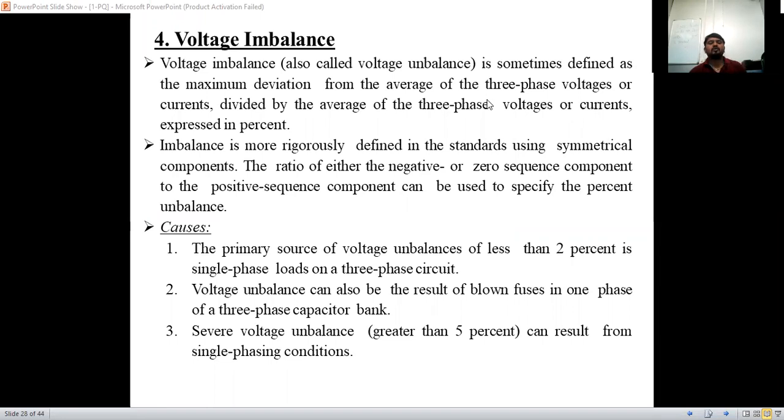Okay, leave that one. These types of voltage imbalances will occur only for single phase loading. Up to your transformer, what will happen? You will get the supply output of the transformer here. The pole mounted transformer is there. You take 3 lines R, Y, B from the substation. You will get a 3-phase 4-line output from the transformer. That is the distribution transformer we are going to use.